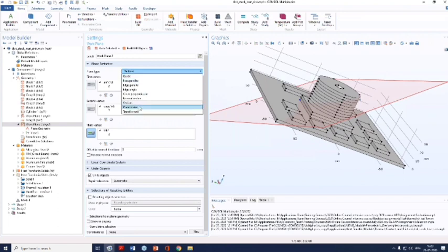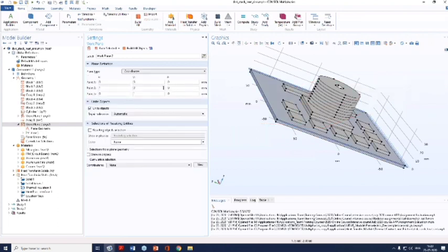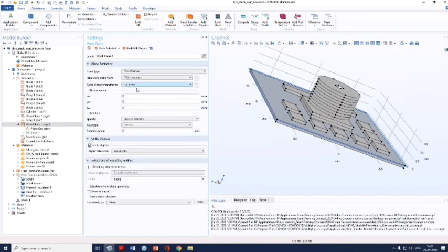And this is the coordinates option, wherein you can explicitly provide the coordinates for the points lying on the plane that you are interested in. And transform is for when you have a previously created plane. Taking the previous work plane reference, you create a transformed work plane from that, meaning if you want some displacement or rotation with respect to the previously created work plane. I guess that's what you meant to say, different options in work plane.